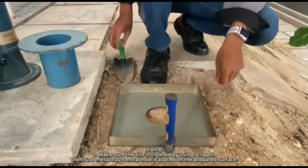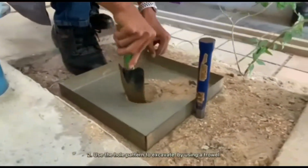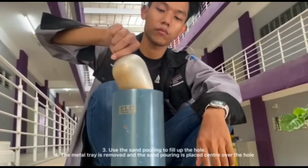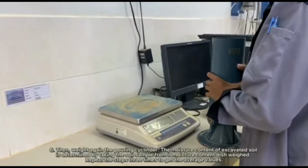Then use a metal tray with a central hole placed on the prepared surface. Next, use the hole pattern to excavate by using a trowel. Next, use the sand pouring cylinder to fill up the hole. And then the metal tray is removed and the sand pouring cylinder is placed at the center over the hole. Then, weigh again the pouring cylinder.